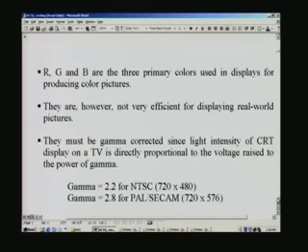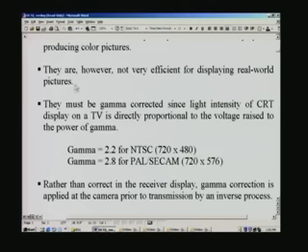So as far as color processing is concerned, we basically have red, green and blue as primary colors for display on the TV monitor that you see, or on the computer terminal that you have. It is basically a CRT display, but they are not efficient in terms of transmitting and processing real world pictures. So, what we do is we need to first do what is known as a gamma correction.